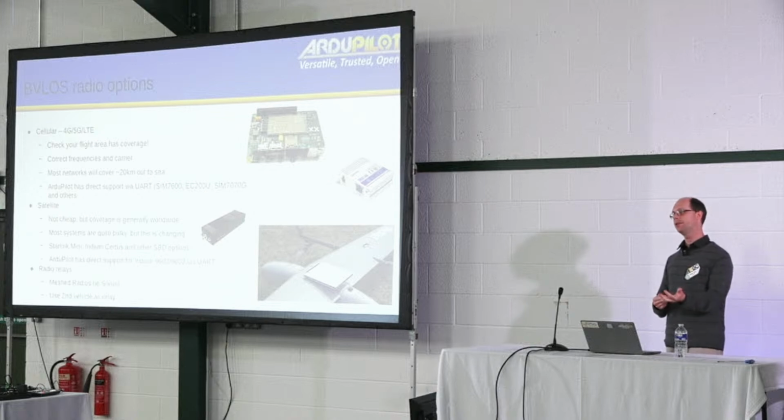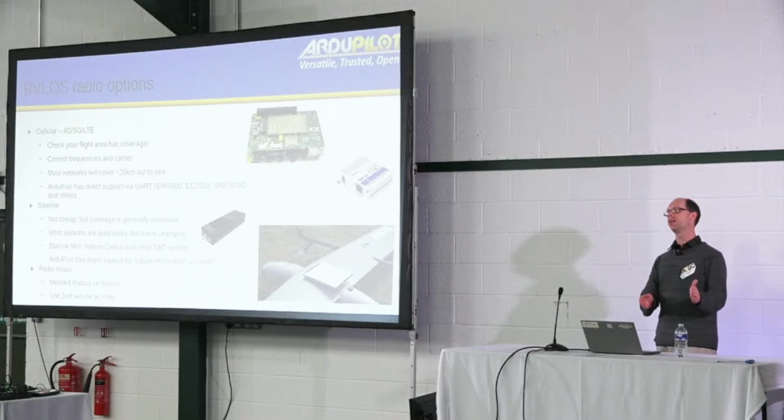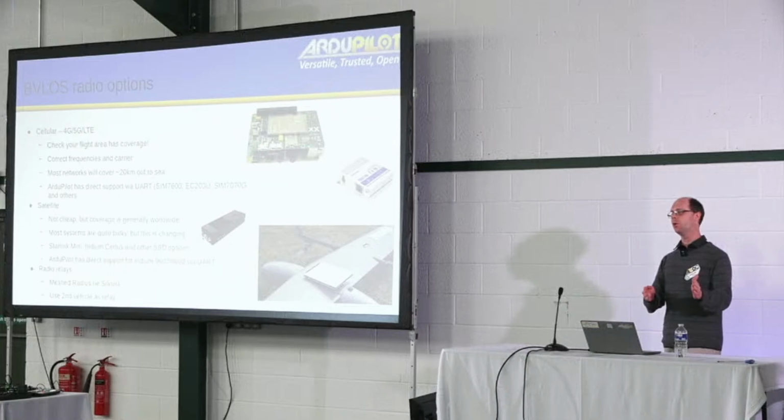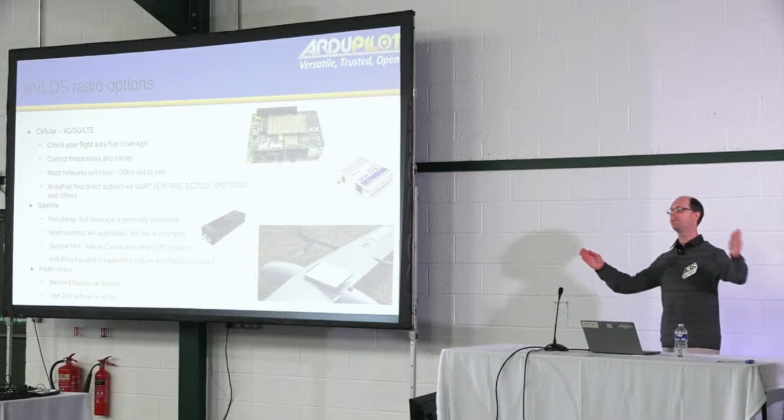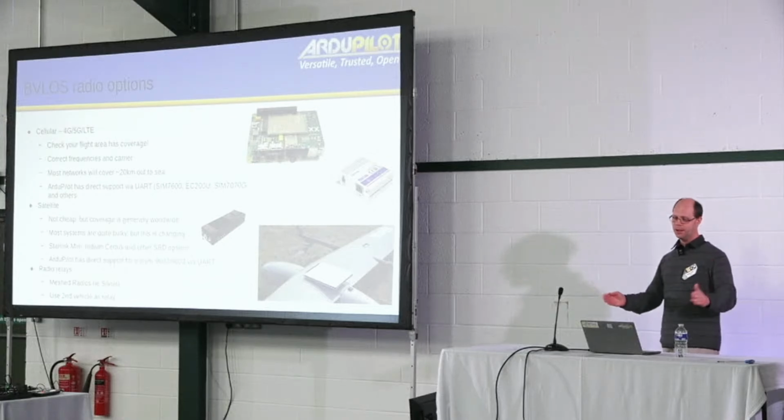However, same cell tower, if you start using your 2-3 gigahertz LTE bands, you're only going to get a few kilometers range, because those higher LTE bands are designed for urban areas, dense coverage, lots of cell towers. And those lower frequency bands are designed for the more remote areas where you have not many people around that you still need to service, but not a lot of users.